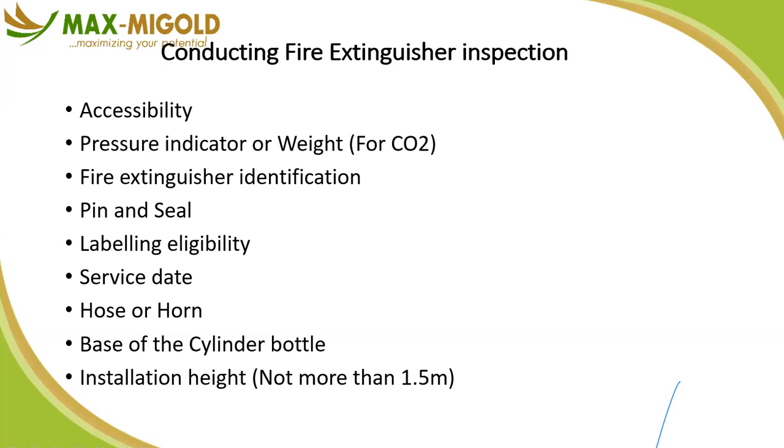The service time keeps changing, but the date you bought it remains unchanged. The location, unless the hazard changes, I want to assume that the location will be the same. But if you change the hazard, maybe you introduce an additional hazard, then there will also be either a change in location or an updated extinguisher list showing the extinguisher that's newly introduced because of the hazard.